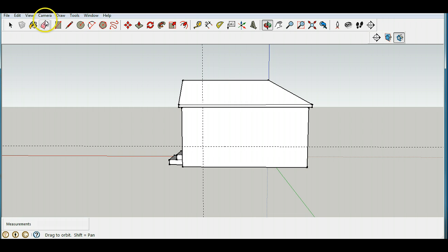So our window is just a rectangle, so I'm going to get my rectangle tool. I'm going to start where the two guides meet, and you'll see there's an X there on the intersection. I'll start to pull the window out, and I'll make it 4 feet by 4 feet. So I want you to pause it, create a bottom guide that's 4 feet from the bottom, and then from where the guides intersect, draw a 4 foot by 4 foot window. Okay, you should have a 4 foot by 4 foot window now that's 4 feet from the side and 4 feet off the bottom of the house.